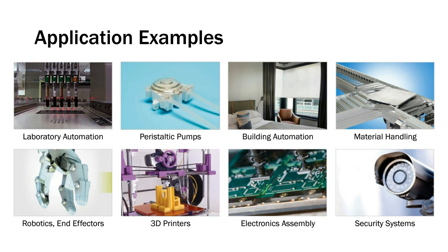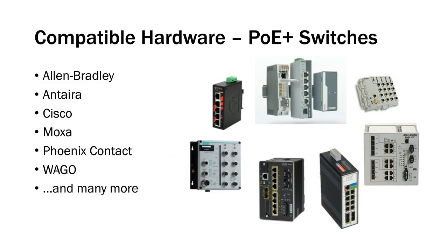Okay, a note about compatible hardware. I hope I made the distinction clear enough in this presentation between plain old vanilla PoE and PoE Plus, Type 1 and Type 2. To get the full power out of our motors, you need to have a PoE Plus switch. Fortunately, pretty much every industrial switch manufacturer out there offers PoE Plus rated ports on some portion of their product line.